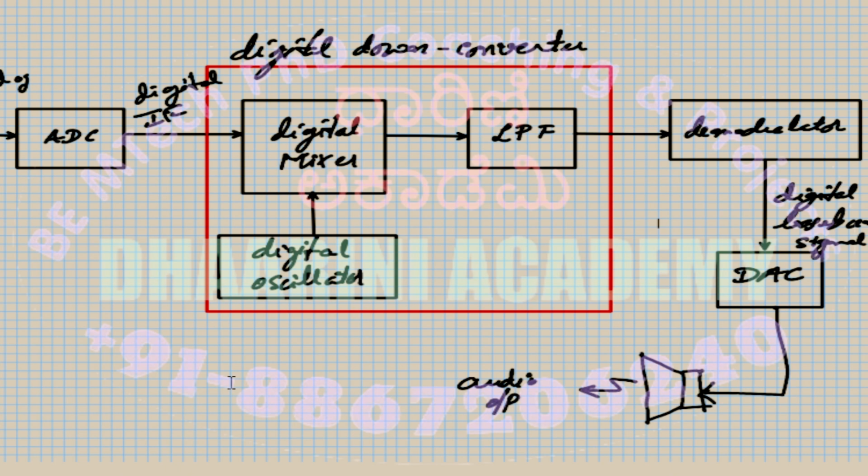Then there will be multiple channels over which you receive the signal. This is to avoid ISI, intersymbol interference. If that is the case, the multiple channels should be combined into a single channel before you go to the next process. That is also an extra burden in terms of circuit complexity. It actually increases the circuit complexity, and you have to add that component at any cost. Again, you may have the FFT circuit over there, and you need an IFFT circuit.